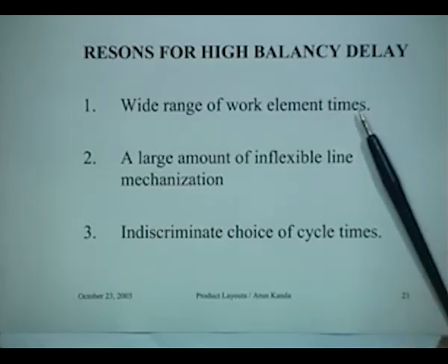This can happen, right? For instance, in your example, the work element times will not be constant for all the operations. So if all the work element times were, for instance, 1 each, or even smaller than this, then you could combine them into getting any operation time. But this does not happen. Some work element time might be only 1 unit, the second work element time might be 12 units, and you have to take it as it is, because the operations are not further divisible.